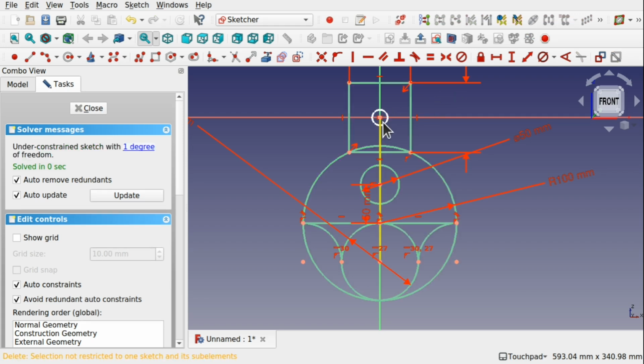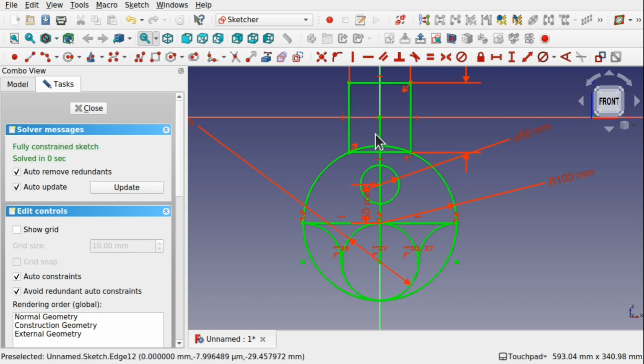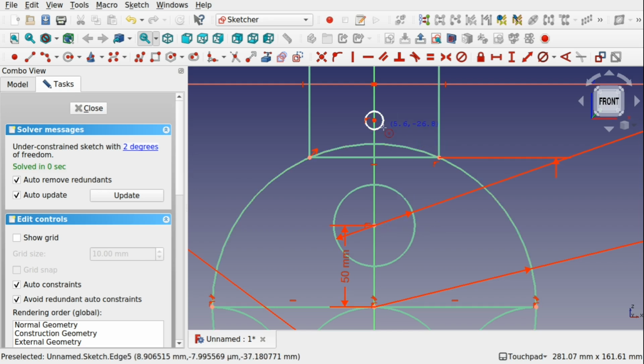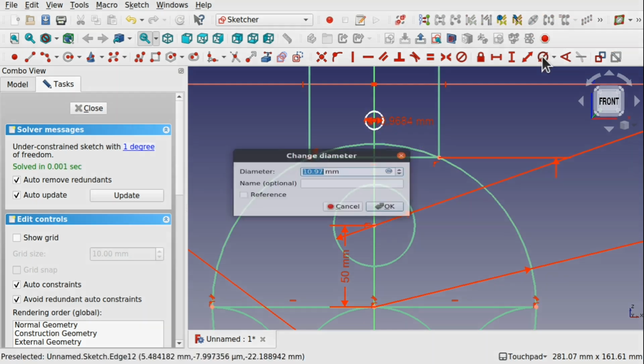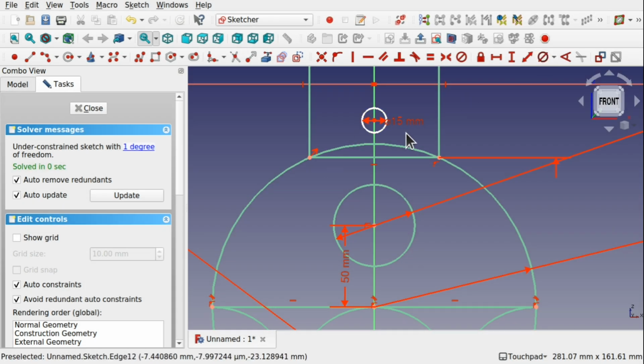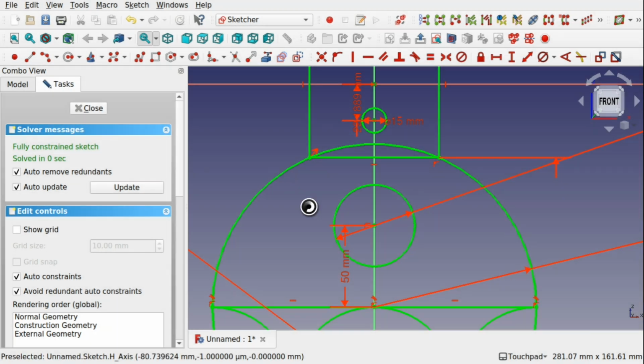radius. Matter of fact, I'm going to delete the whole circle, and I'm looking along this line and thinking to myself, I'm going to actually delete the line, click on the line, and create the circle that's coming around about here. So this is going to be the connection to the connecting rod, and set that diameter to be 15 millimeters there. It's better. And now I can set some height on here. 22, let's go for 20 mil.